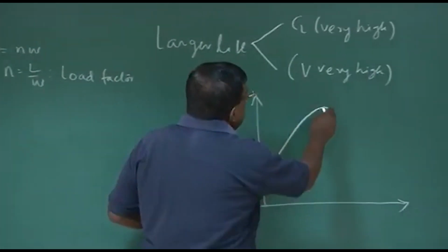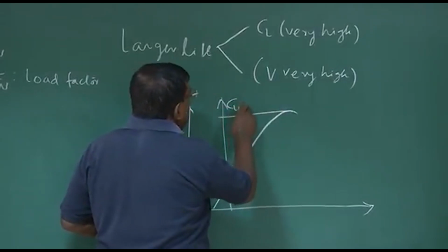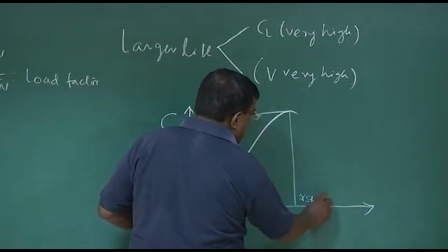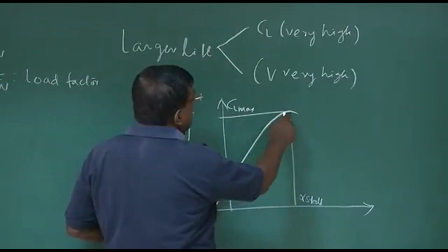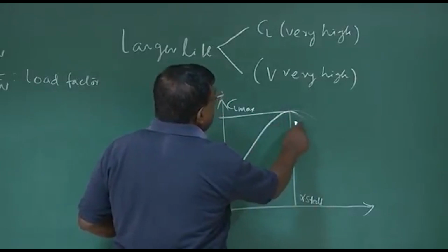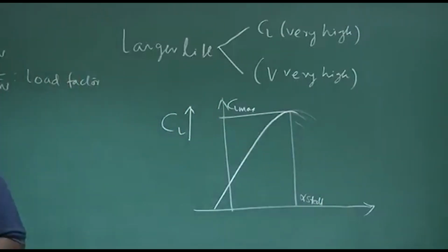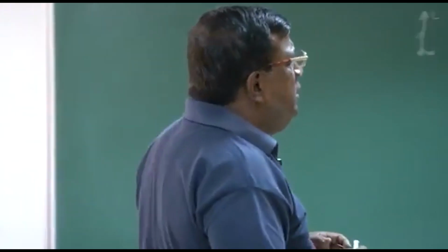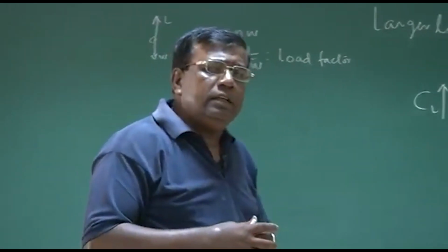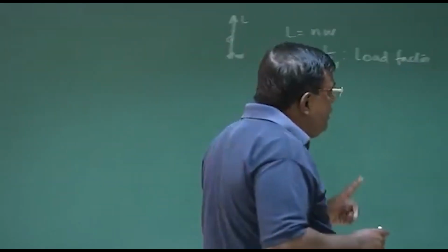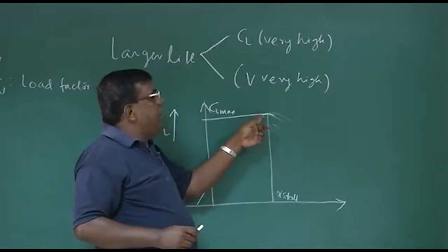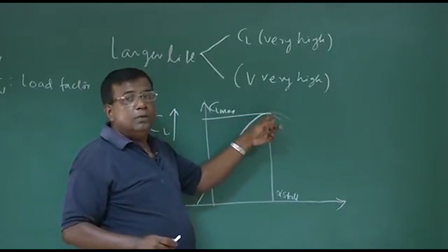But the point is this, there is a finite value, I call it CL max, and corresponding to this is alpha stall. Why alpha stall? We know by now that beyond this angle, the flow goes into a stall region where there is flow separation, vibration, oscillations of flow, a lot of increase in the drag, and so many complicated things happen. I am not going into detail, that itself is a subject. But the point I understand as a flight mechanics man is that there is a limit beyond which if I fly, I will be going into a danger zone, right?